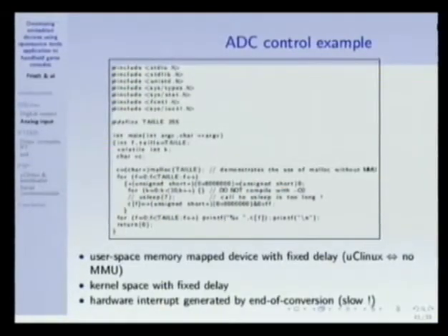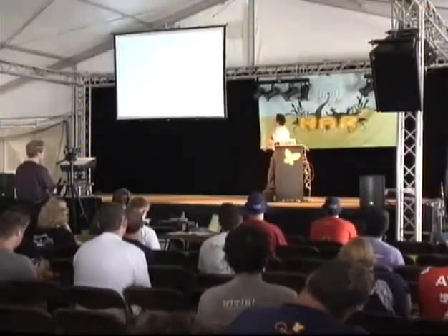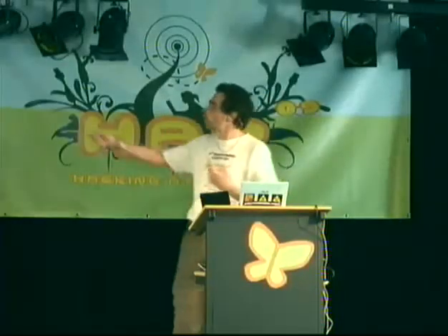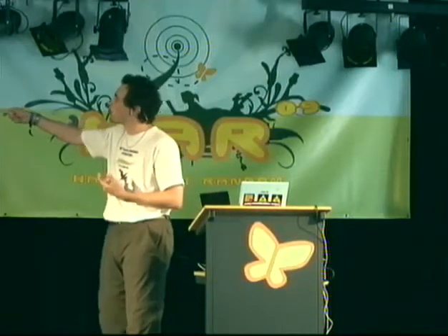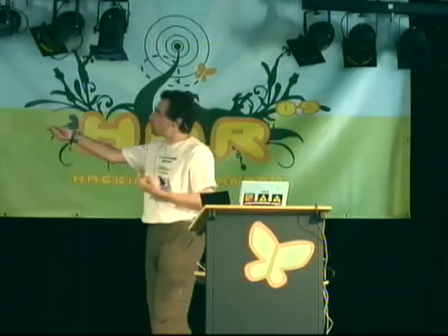How do you write a piece of software for controlling this ADC? Exactly like we did before, we will address this 8 million address. We say that we are using an unsigned short. We want to read 16-bit. But this time, instead of assigning a value, we will read a value. So this time, instead of having a write signal being triggered, we have a read signal being triggered. And at this point, the ADC will provide its value.